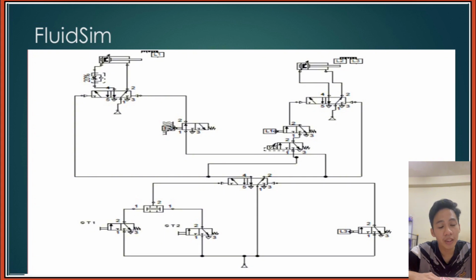The number 14 is pushed, so the clamper will extend with a speed control valve, so it will extend slowly to protect the part from damage. This is one of the safety features.